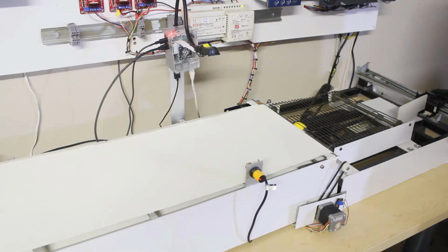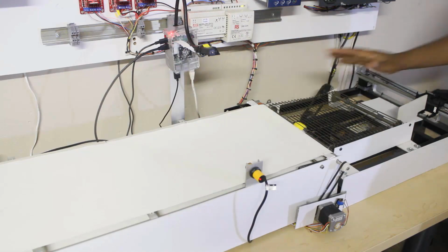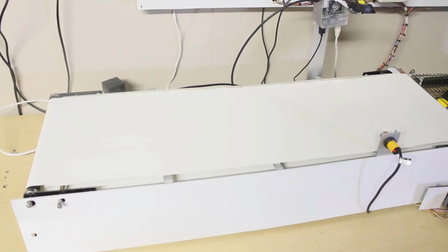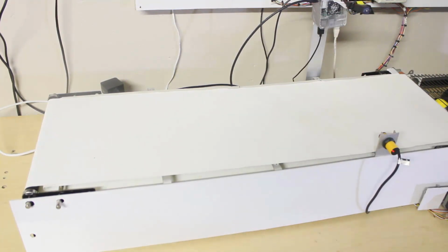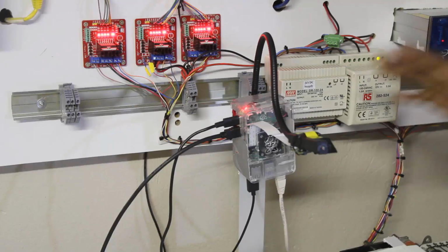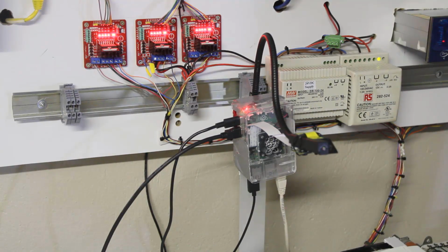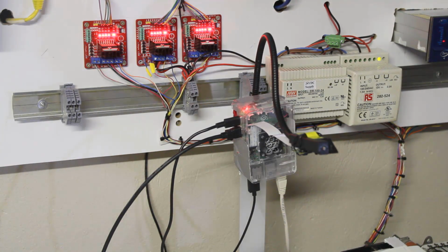It consists of two conveyor belts, the main conveyor and the small conveyor. On the main conveyor belt, I've got a proximity switch to detect the presence of a product. It is normally high and produces a low voltage on product detection. So this serves as a signal for the controller to stop the conveyor belt for product inspection. And then here, I've got a high definition camera connected to a Raspberry Pi 4B+. So upon product detection, control is passed onto this computer vision system to identify a product and send information to main control for appropriate product sorting.